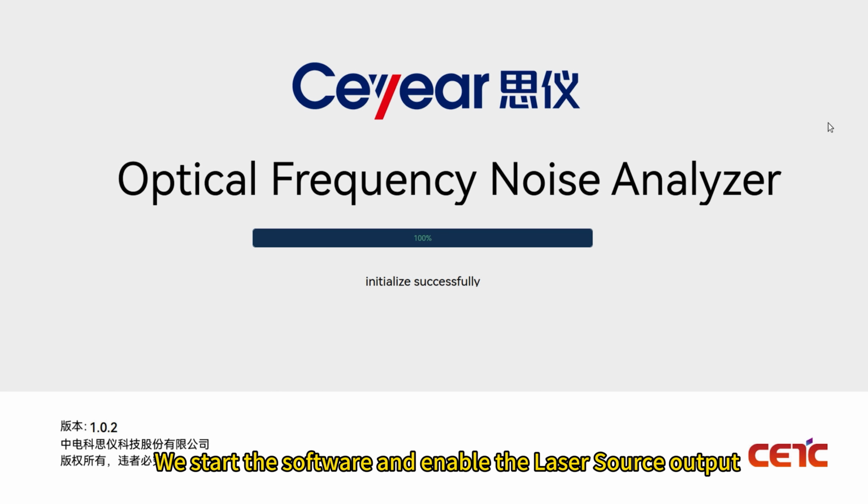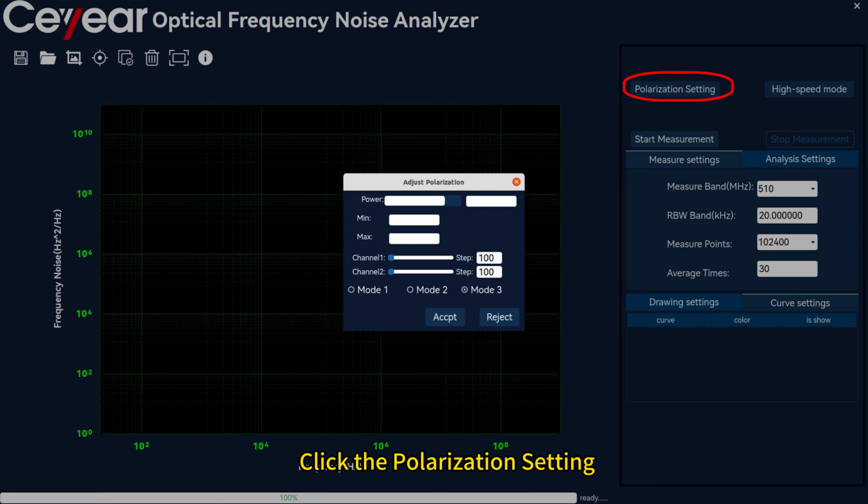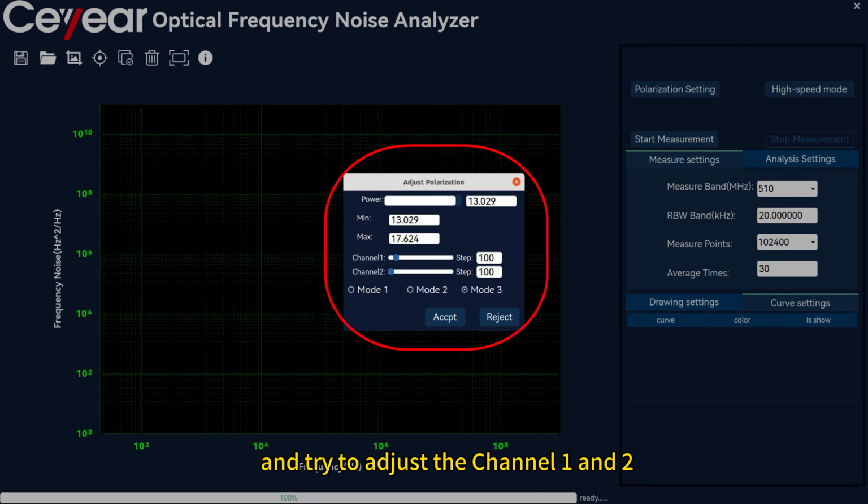We start the software and enable the laser source output. Click the polarization settings and try to adjust channel 1 and 2 and choose mode 1, 2, or 3 to get the maximum power. The current maximum power is about 17.6 dBm.